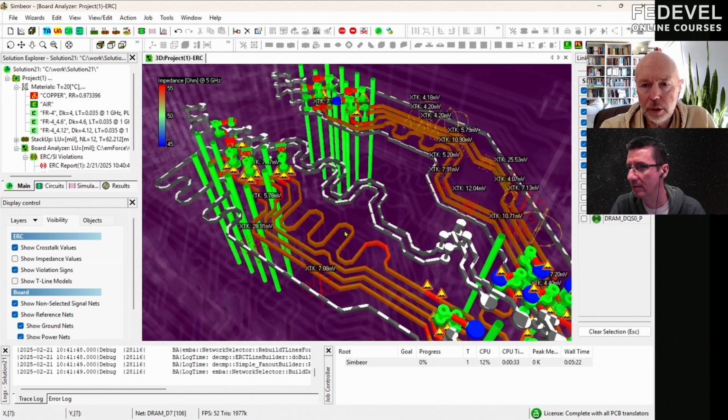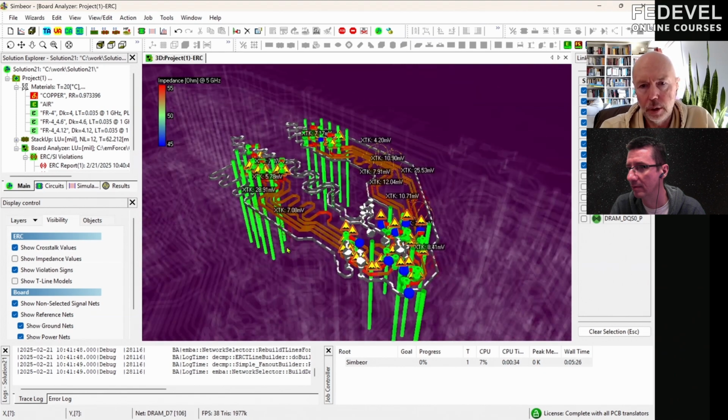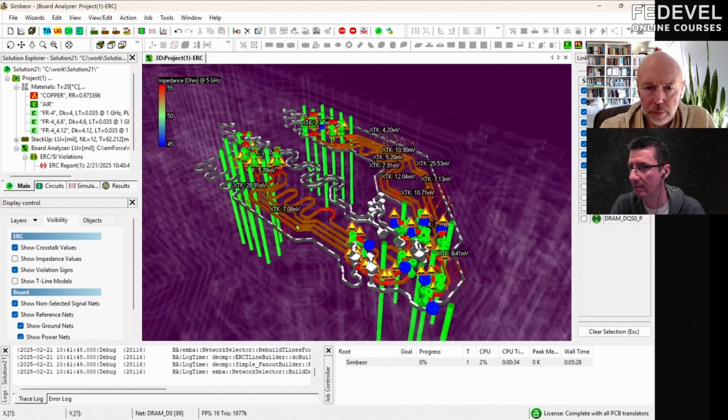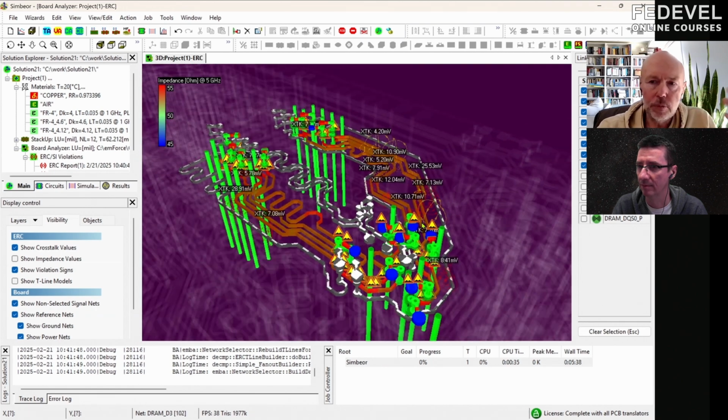To evaluate actual crosstalk from simulation, a quasi-static field solver was used to evaluate every cross section, every parallel section found on the structure. But in reality, you need end-to-end crosstalk. And for this purpose, I will use fast analysis.